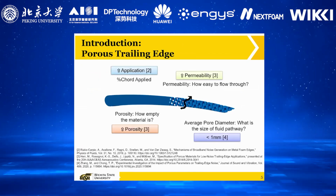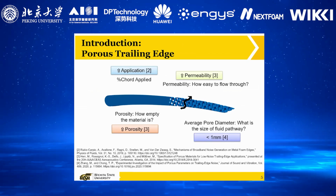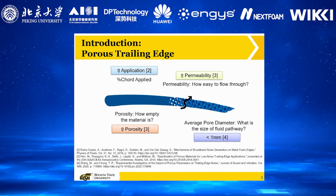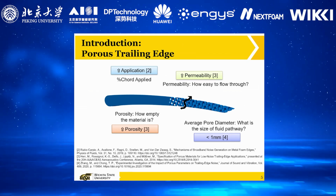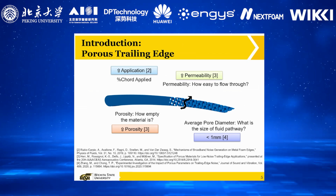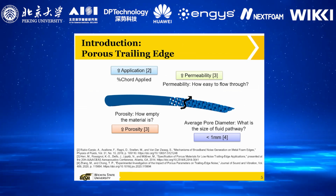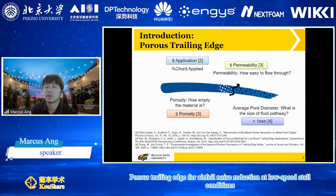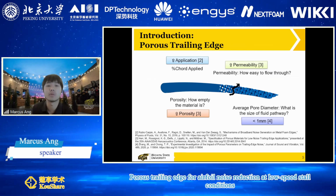I'm not going to go too deep into this topic, but essentially this is what a porous trailing edge looks like. Essentially, we apply porous media to the trailing edge. There are many factors that play a part, depending on things like the percentage of application, permeability, porosity, and the average pore diameter. Here are some studies where they've done parametric studies on this and seen what gives you the best performance.